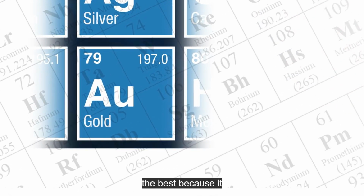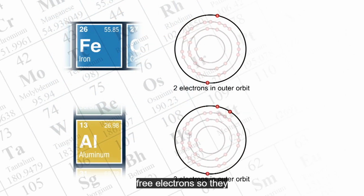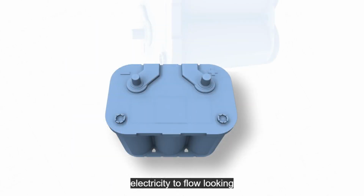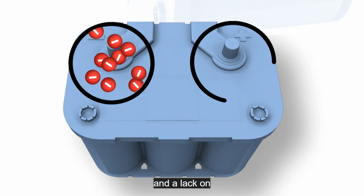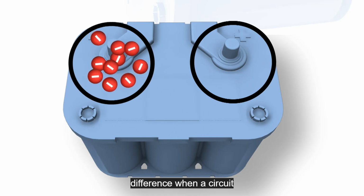Gold is the best because it doesn't oxidize as fast as the other two. Iron has 2 and aluminium has 3 free electrons, so they are not quite as good at conducting electricity. It's the free electrons that allow electricity to flow. Looking at a charged battery, there will be an excess of electrons on the negative terminal and a lack on the positive terminal. This is known as a potential difference.